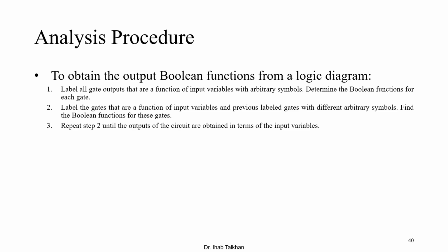In this slide, we are going back now to combinational circuits, where I'm going to give you another way to solve a combinational circuit. In the previous lectures, we gave you a function description, and then you constructed a truth table. From this truth table, you can get an equation. For this equation you can use either a K-map or identities in order to optimize it. But after that, you draw the hardware. Here I'm going backward. I'm going to give you the hardware and ask you to go back and give me the relationship between input and output.